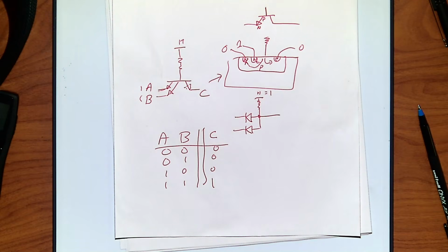So that's kind of cool, to be able to do that with a single transistor. Now, the problem is most of these are not particularly strong. Because remember, if it's a 0 on one of the inputs, the output, just like with diode logic, is controlled by that original signal. But we just use some of it to open the gate, so it won't be quite as good of a value.